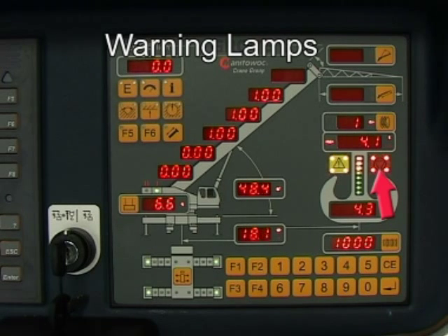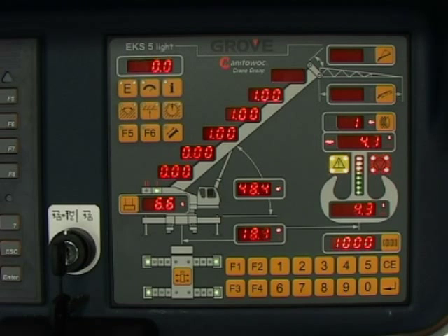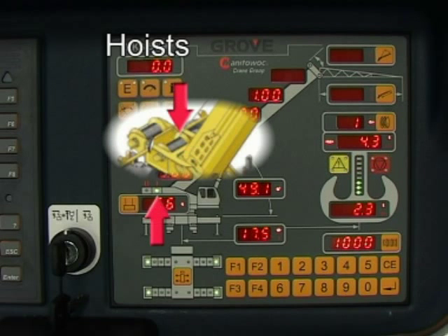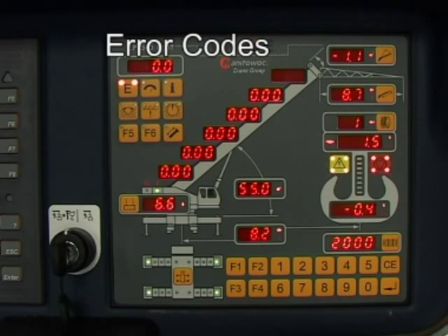or an error has occurred. A continuous audible warning buzzer will also be heard. All crane functions that could affect the safety of the crane are now shut down. The LEDs will light up to indicate which hoist is active. Flashing LEDs on the error button indicate detected errors.